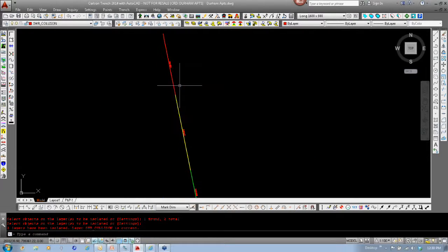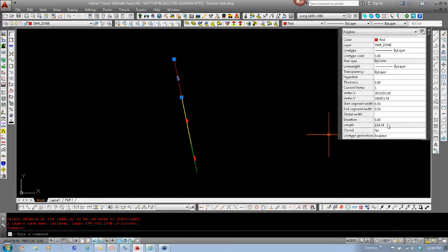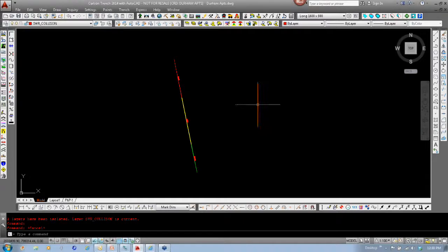so now you can see that it basically goes in and draws polylines where you can select the lengths of how much is between 0 to 6 feet, how much is between 6 to 8 feet, and those depth quantities for your takeoff quantities. I wish I'd have had this a long time ago, I can tell you that, because going in and measuring it off profiles and doing things like that takes quite a bit of time, whereas this program spit it out very, very quickly and very easily.